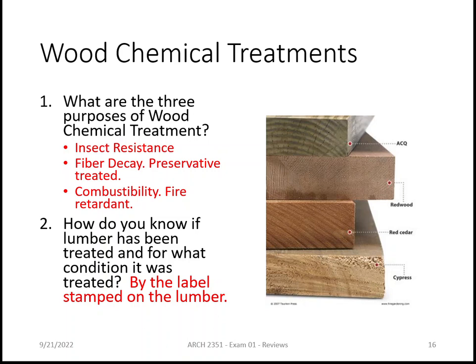How do you know if a piece of lumber has been treated for any of those 3? Stamp. If it's not stamped, I don't care what they tell you or what it looks like, you assume it is not treated. Because if it's been treated properly, it will have a stamp on it. And most often it will be burned into the wood, so it can't be gotten rid of or faked and added on. Though you could make your own brand, I guess.